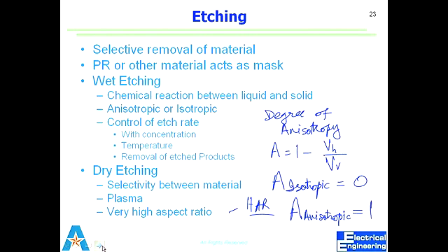In case of wet etch, anisotropy has slightly different concepts. Anisotropy is the preferential etching along different planes of the crystalline structure. So we want maybe something that etches 100 much faster than 111. What we end up with are shapes like an inverted pyramid, or slanted walls which have a very exact angle with the x-axis. That's what is called anisotropy or anisotropic etch for wet treatment.